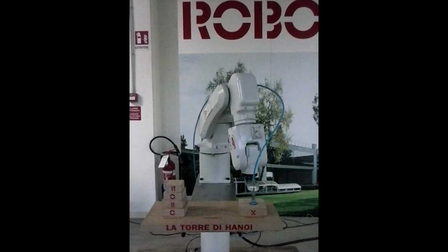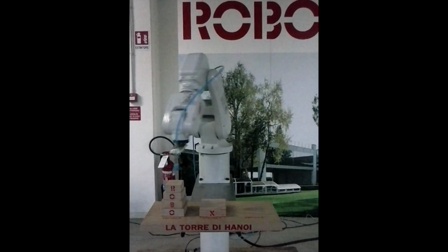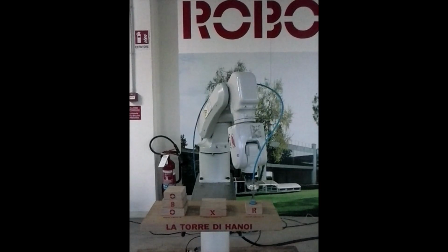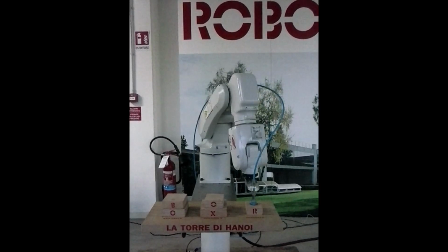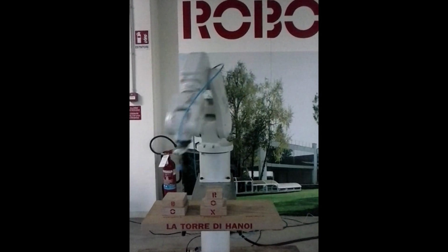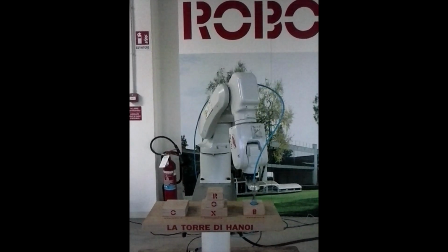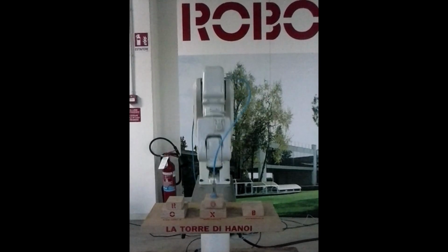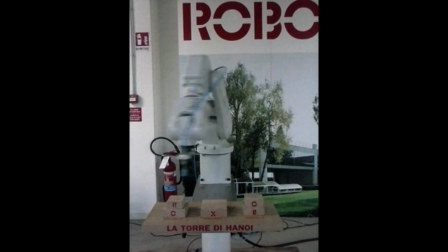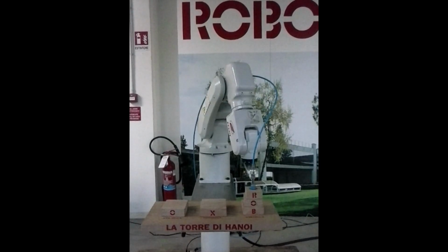The joint motions are the ones that just request a begin point and a final point, and the system will move all the joints of the axis group in order to reach that point, while a Cartesian movement is like a ray in space connecting two points, the origin point and the target point. This means that the path will be a line.